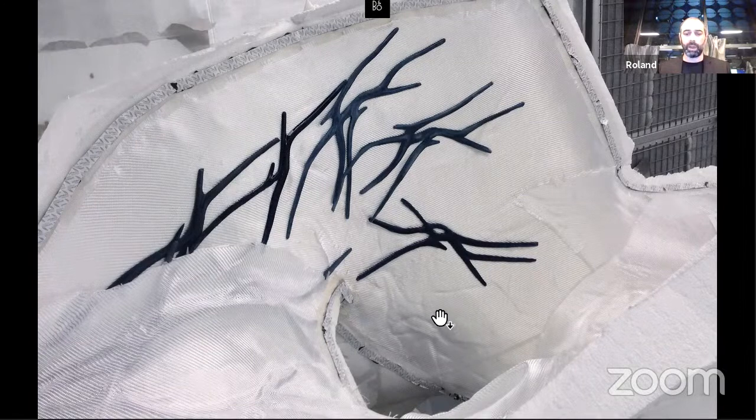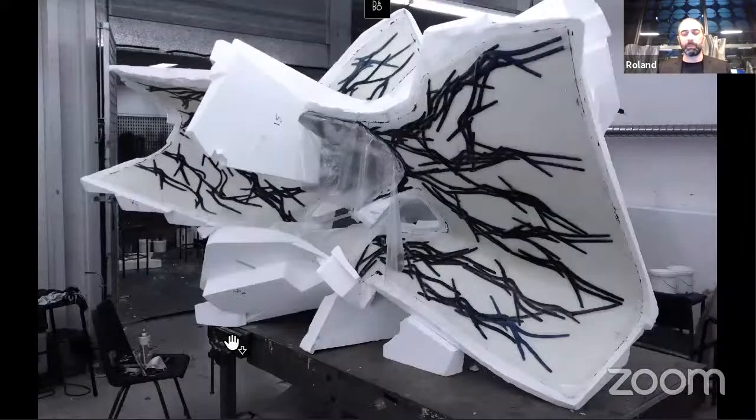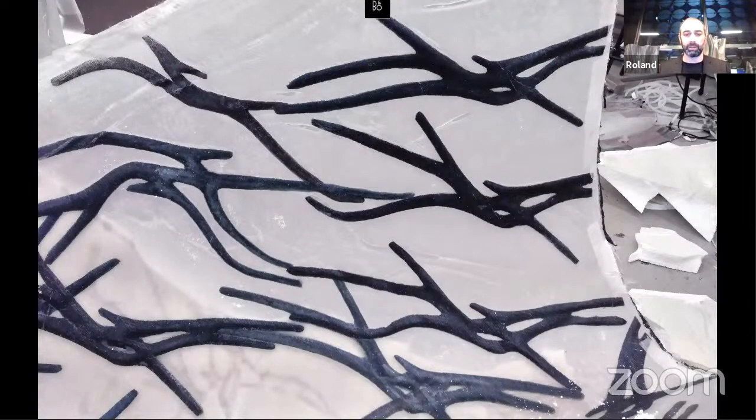You can begin to see towards the bottom of this image the way the imprint of the agent bodies is milled into the mold. This becomes a way of locating them as we're fabricating, and also enables the surface to have its articulation on both sides in 3 dimensions. More fiberglass was then laid over those, and then we use a process known as vacuum infusion, where we cover it with a vacuum bag and draw resin through under vacuum, which gives a very efficient composite. As I said, less than 1 millimeter thick.